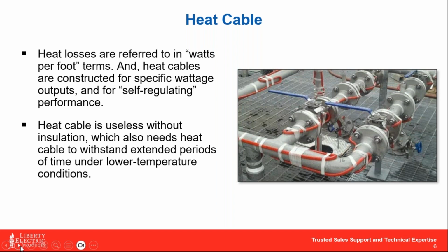So, to reiterate what we just mentioned a moment ago on that previous slide, heat trace cable is basically useless without insulation to cover it and hold that heat into the skin of the pipe. If you could imagine, looking at this picture here to the right, if we had these heat cables working on a 30-degree day, they're emitting literally 95% of their heat to the ambient air. So again, it's not doing you much good for whatever's inside the pipe, okay? So again, insulation goes hand in hand with your heat trace cable.